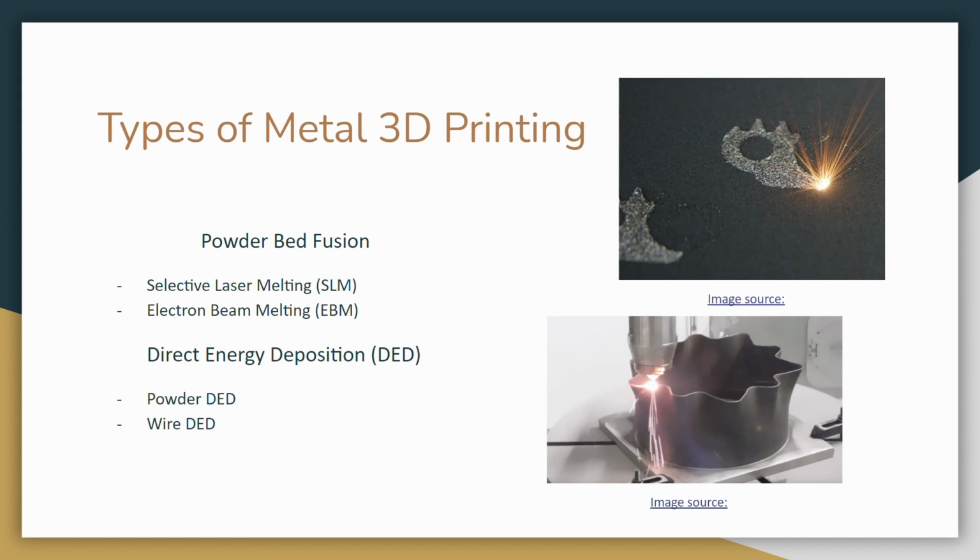SLM stands for selective laser melting, and it deposits a thin layer of metal powder that is then melted into a solid film via the use of powerful lasers, which slowly accumulates into a finished product as new layers build upon the previous ones. This process uses a potentially hazardous metal powder that requires skilled technicians to run. SLM printers cost upwards of $1 million US.